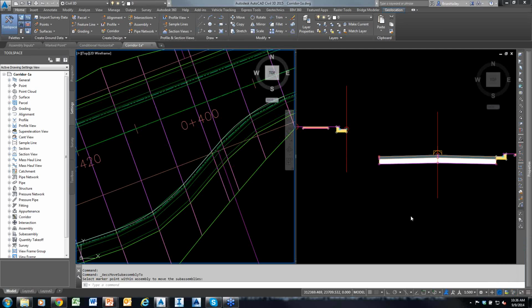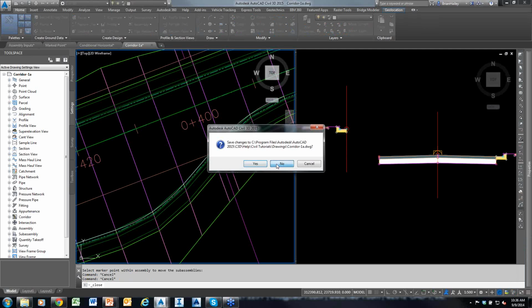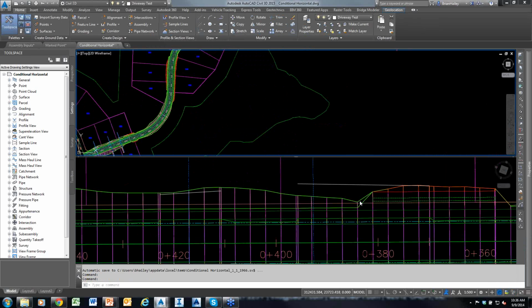All right, David asks, we have to add safety berms after we build our roads. How would you do it, 3 feet high? It's part of the road cross-section, so I would just add a berm to the road cross-section. So David, you work in mining a lot, so I would just add that to my road cross-section.